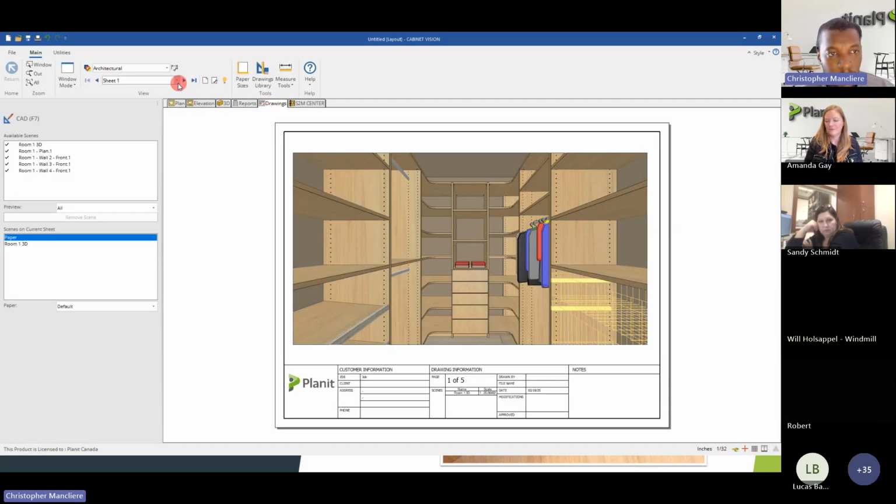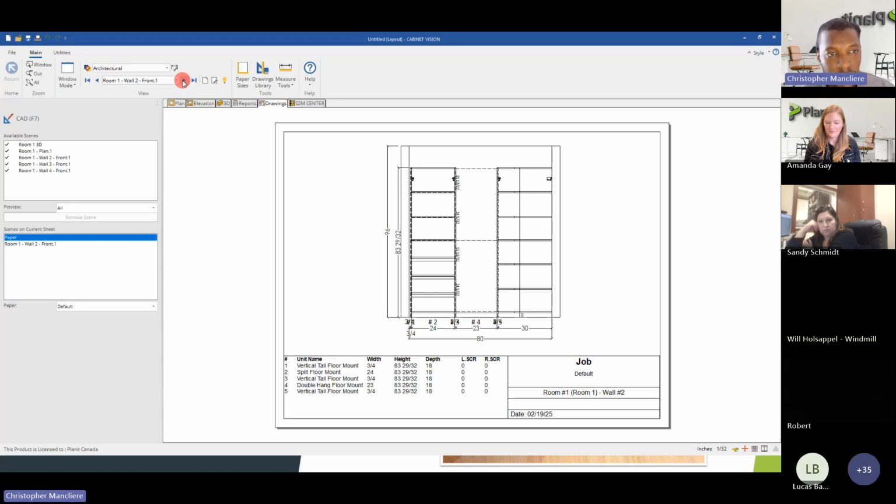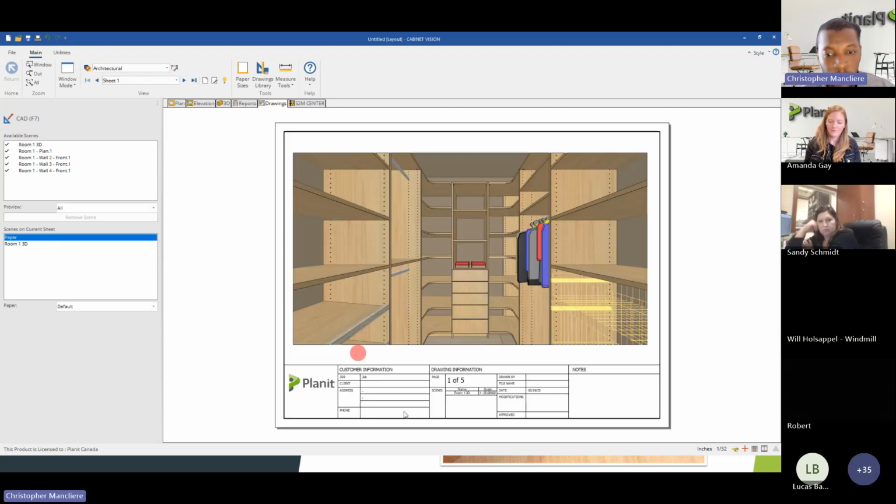And in the drawing tab, now if I go to the next sheet, now this is my automatic plan and automatic elevation. Of course, you can customize the actual template. This one is just the default one, but you can see in one click, I created those plan elevation, and my cover page is still there. So right now, my package is made of 5 different pages.